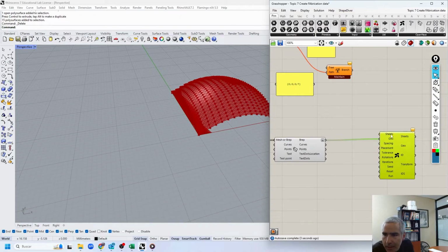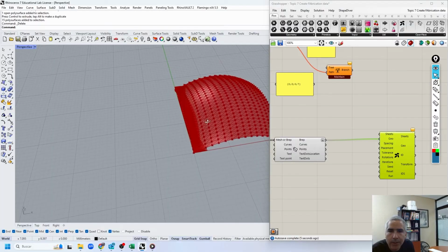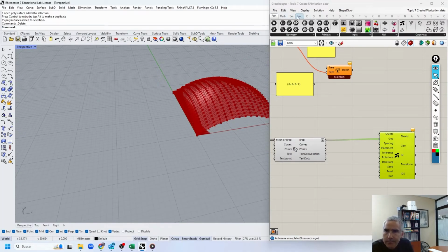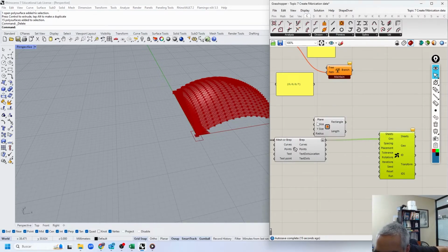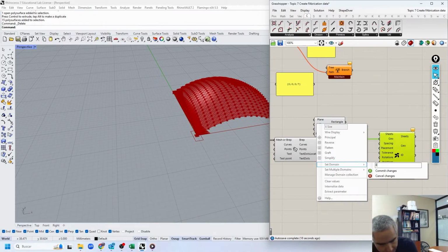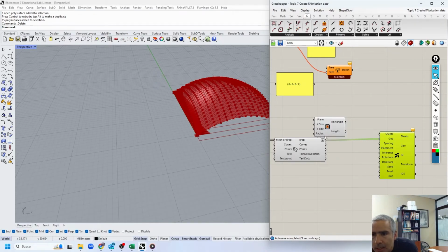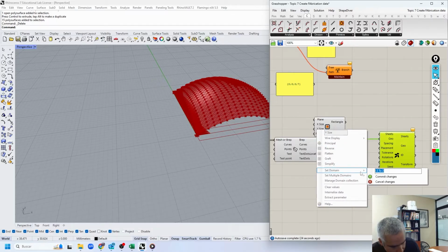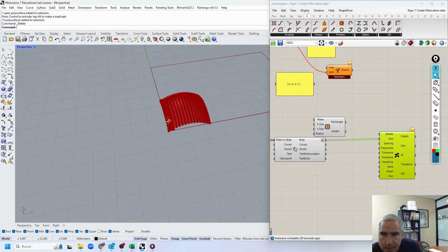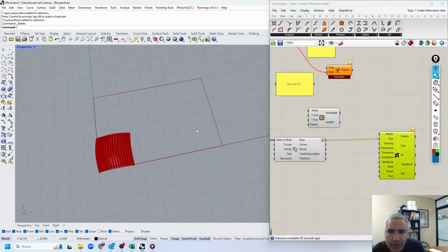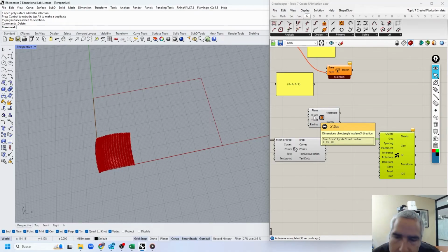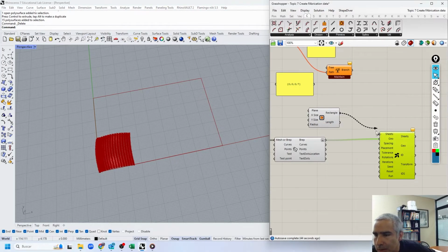And then I'm going to set up a rectangle as a sheet. This rectangle will have size 0 to 90, as if it was centimeters. It can be meters or something else. 0 to 60. So that's this rectangle here. It can be a different rectangle, it depends on the boundary of the laser cutter. But the laser cutters here at the university, and many of them, have 900 by 600 millimeters. So I'm going to use that as a sheet.